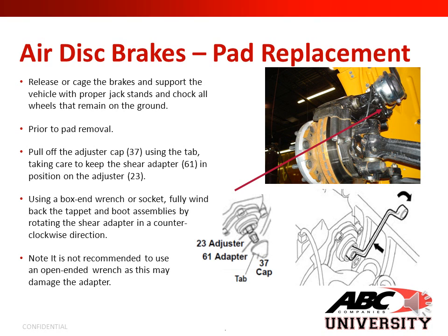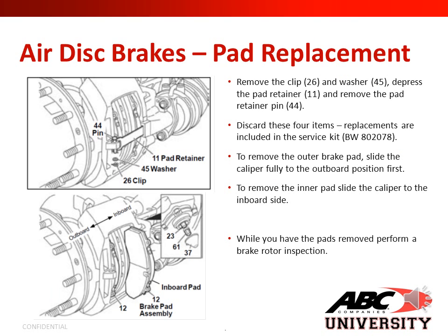Using a box-end wrench or socket, fully wind back the tappet and boot assemblies by rotating the shear adapter in a counterclockwise direction. Note, it is not recommended to use any open-ended wrench as this may cause damage to the adapter. Next, remove the clip number 26 and washer number 45. Depress the pad retainer number 11 and remove the pad retainer pin number 44. Discard these 4 items. Replacements are included in the service kit, part number